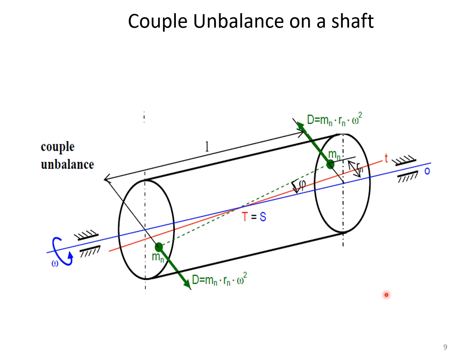Now let's try to understand what exactly happens when the shaft is not dynamically balanced. Let us say that this blue line is showing the axis of rotation, and the red line is showing the axis of center of gravity. Then the center of gravity becomes inclined to the center of rotation, and in such cases there will be a couple generated, and because of this couple there are unbalanced forces on the bearings. So our aim is to balance the unbalanced couple and to balance the unbalanced forces.